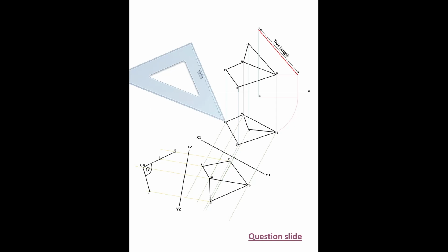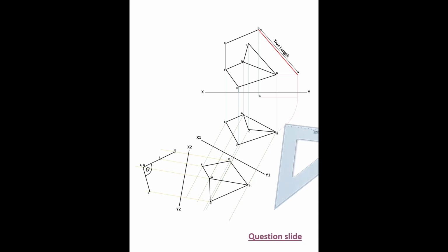So the next part of the question is our sliding set squares. We line up our sliding set squares with A and E, and we know that G and F are parallel. So we slide it up to A and E, and we slide it all the way up until it reaches G, and we draw in our light line, and we bring the other one directly up because we know that E and F are also vertical. So we found our point F in the elevation now.